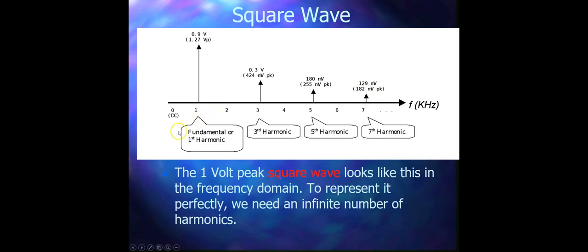So we see that all these harmonics are present in a square wave signal, and we need to notice how these signals start to get smaller around 11 kilohertz as you go further. This is why most technicians stop analysis at the 13th harmonic, which will be somewhere here. And the 17th harmonic is very small, and it is usually barely visible. If you use the spectrum analyzer, you will see it looks like a bump on the graph.